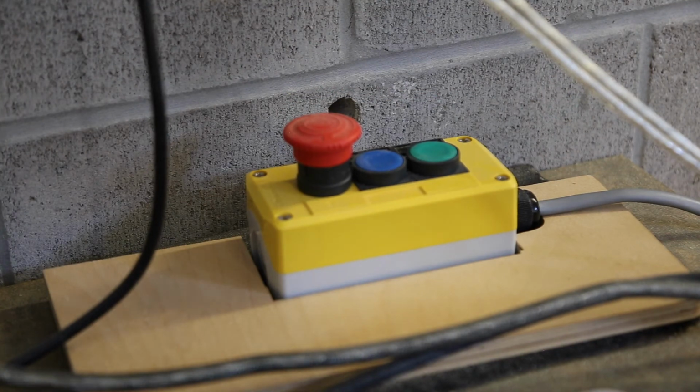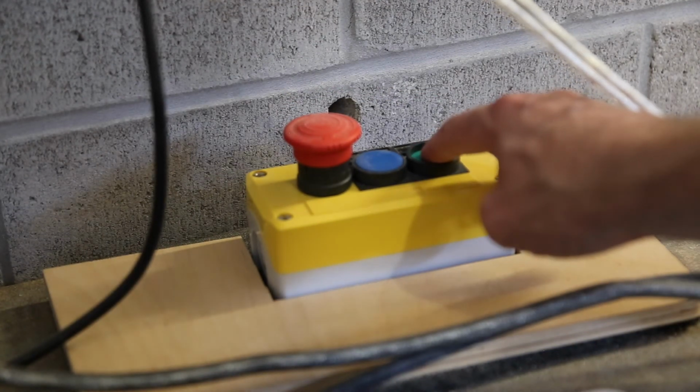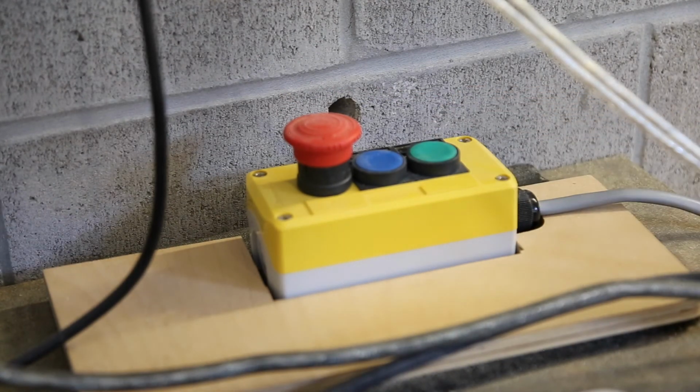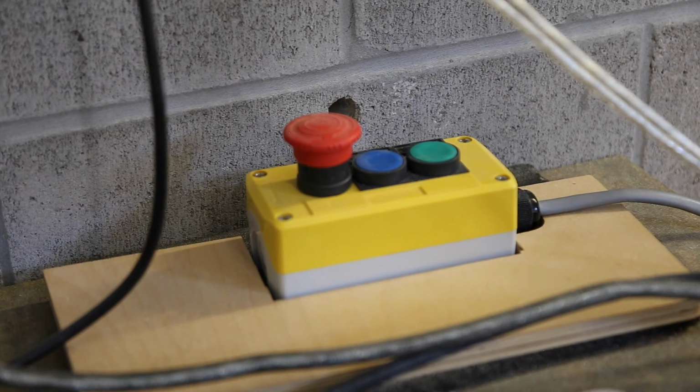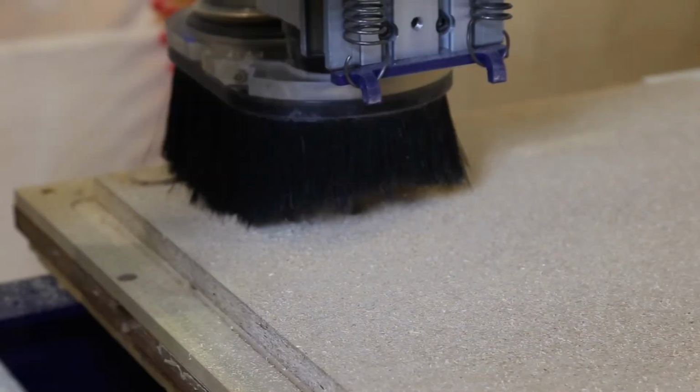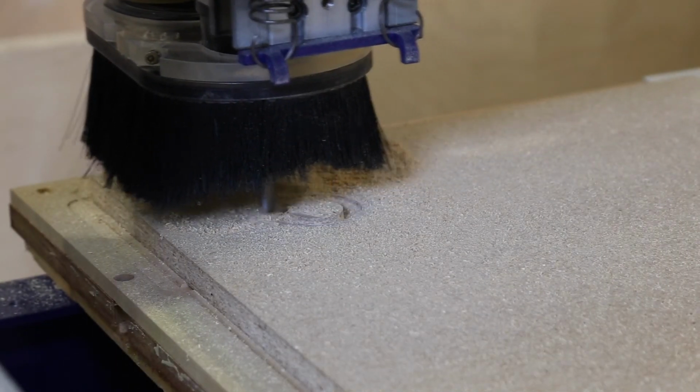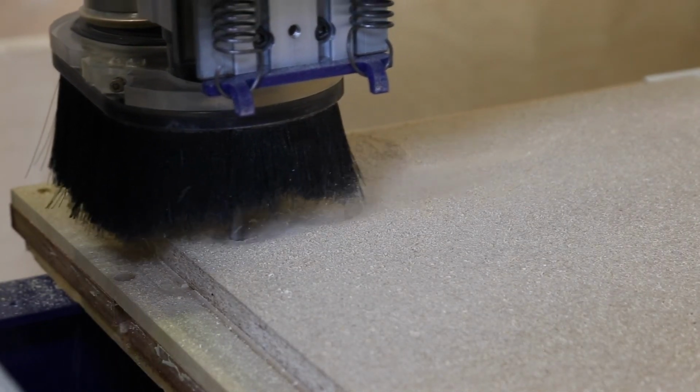Always turn the spindle on before clicking OK or hitting the Enter key. Failure to do so will start the movement of the gantry without the spindle moving, and will drive the stationary bit into your workpiece, potentially breaking the bit and moving and damaging your workpiece.